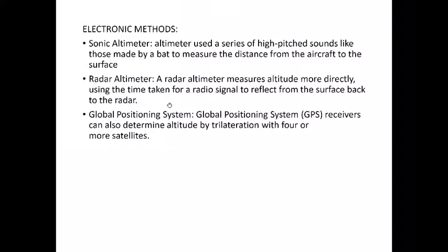You study that in the next semester, and that's a very quick method to find out elevation differences in a large area. So instead of using your instrument, the auto level, and taking a lot of random points, a lot of observations, and then performing calculations, that is replaced by these new instruments. But obviously, we don't have them everywhere, so we need to know the basic ones as well. And then we have the GPS. GPS doesn't only give you latitudes and longitudes, it can also give you altitudes. So if you have a good one, you can also use that to find out elevation differences.